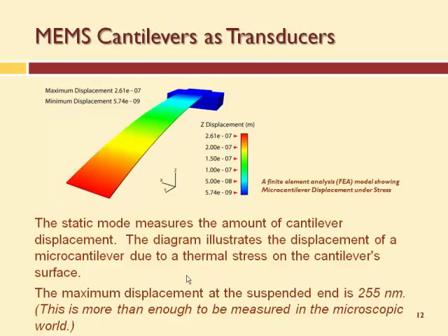Yeah, there's an old school way to do this. You know how they used to do this stuff? They used polarized light and plastic. You take lucite, which is a birefringent material. If you send polarized light through lucite, it'll rotate a certain amount. If you stress it, it'll rotate a different amount. They put one polarized sheet underneath the lucite and another sheet rotated 90 degrees relative to the one underneath it.